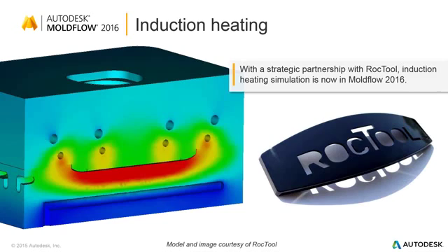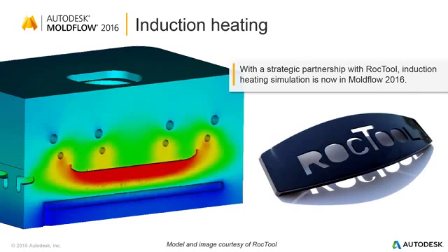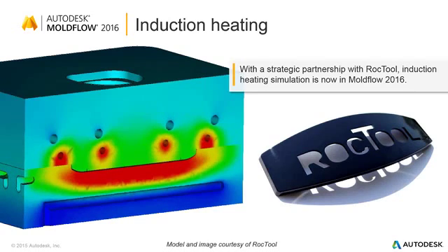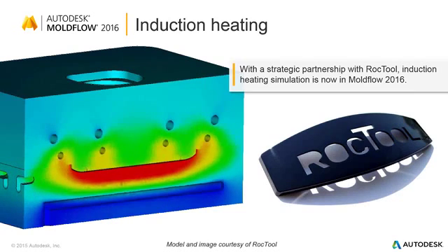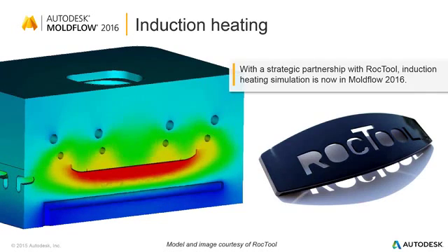Just in a fraction of a second, that tool will be heated up in the location where you need it, close to the mold surface temperature. But it's a very local effect, which means you don't actually have to cool the entire mold down, which is something you would get with more traditional rapid heating and cooling technologies that are out there.